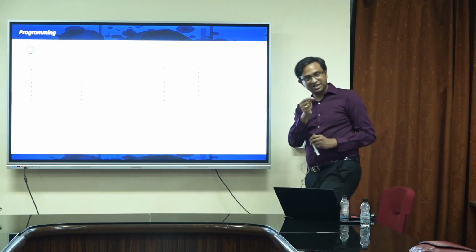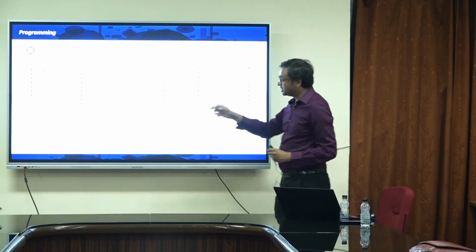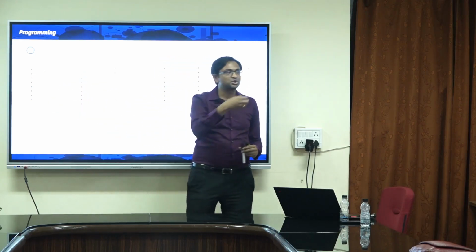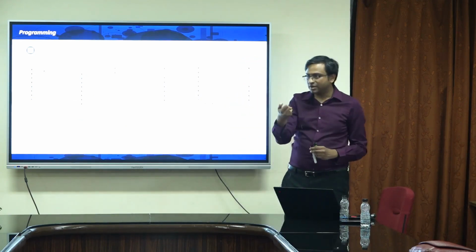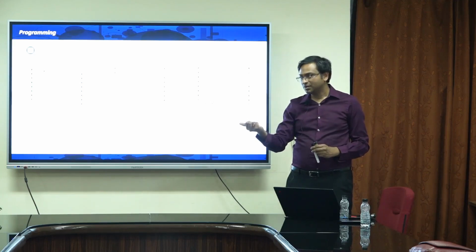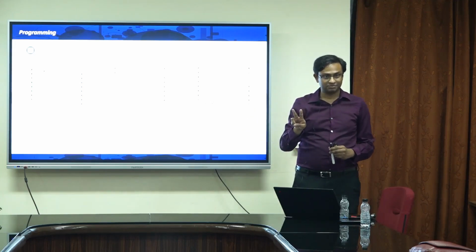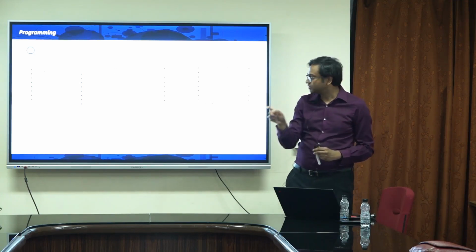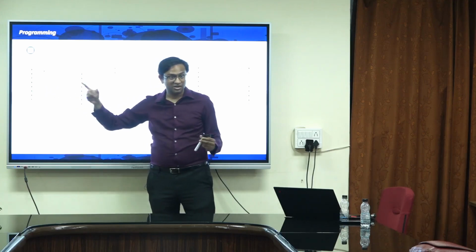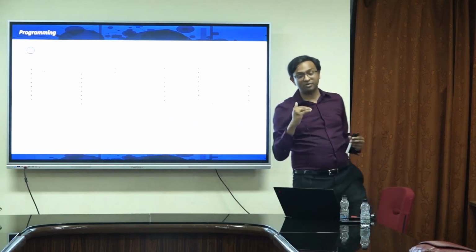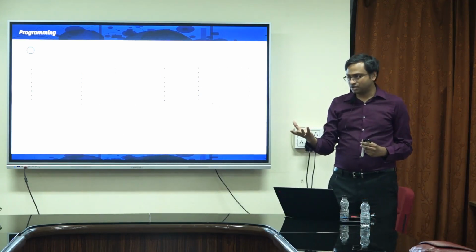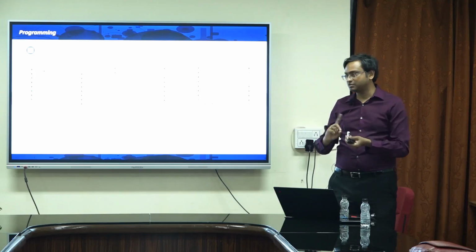And then it's very interesting. I showed you two states, 1 and 0, but that's really not the case. I can make the device at different states, because if I store different amounts of charge, now instead of 0 and 1, I could do 00, 01, 10, 11. That is like storing 2 bits of information. For each state, I get one conductance. So you can now start storing more information in a single device. Ideally, in digital logic, when we talk about a transistor, you can only store 1 or 0.